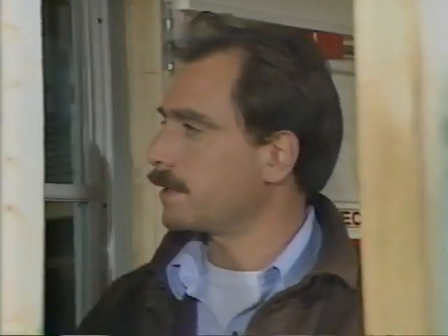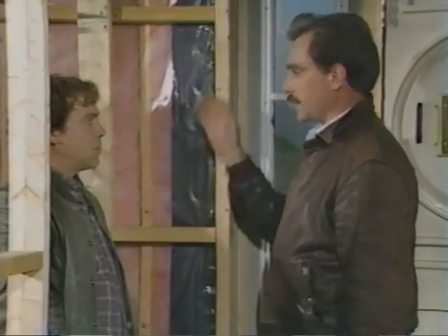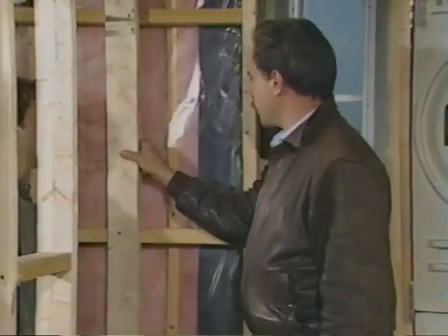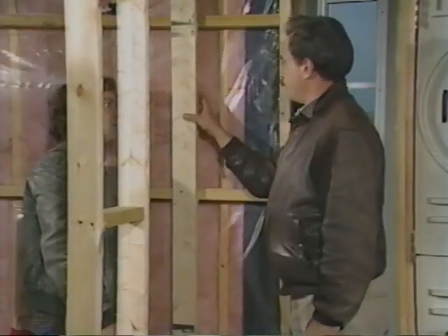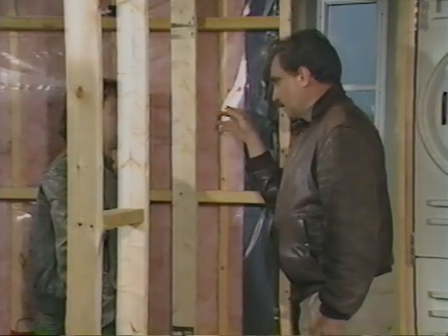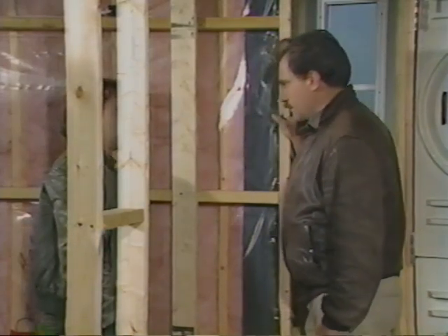Well, the smoke seems to be just drifting up on its own, but not because there's any wind coming in. Sure isn't. The reason for that is because we've very carefully seen this poly barrier put in throughout the entire building. Goes up the walls, across the ceiling, everywhere. The builder has very carefully detailed it, for example, around partition walls here, where you can see that the poly has been run right through, and the wall has actually been installed after the poly has been put in place in this particular situation.